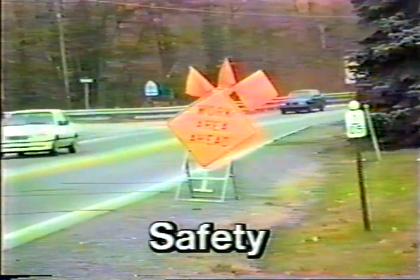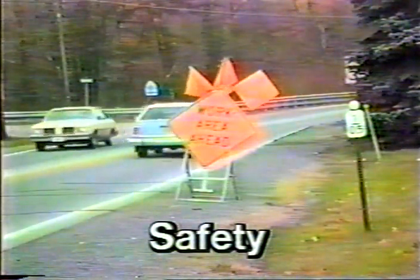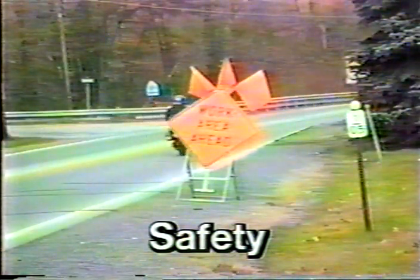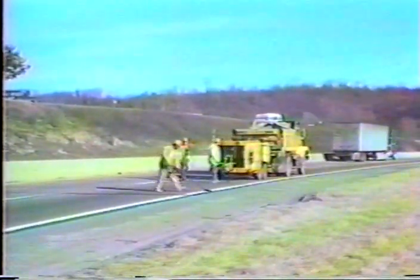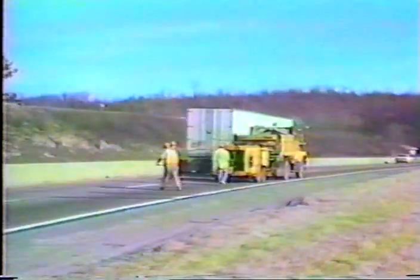Safety is an important part of crack sealing operation. It starts with traffic control. Traffic control must be in accordance with Publication 203. Crack sealing involves two major hazards: using very hot material and working near moving traffic.